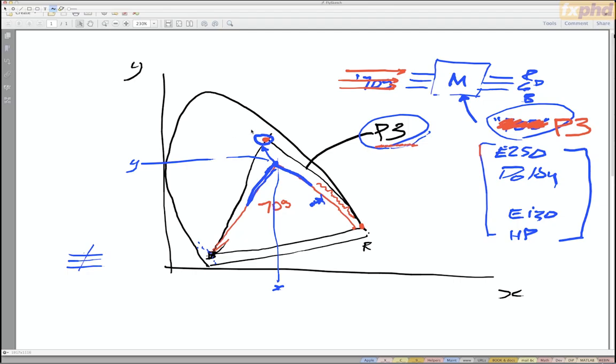Obviously, we hope they're a tiny bit wider, because we'd like to make sure that P3 data gets displayed absolutely correctly. So typically the native primaries will be a tiny bit wider than P3. And when you set up P3 in the user interface, there will be a matrix in the signal processing, but it'll make a tiny adjustment, bringing the display capability into exactly textbook P3.